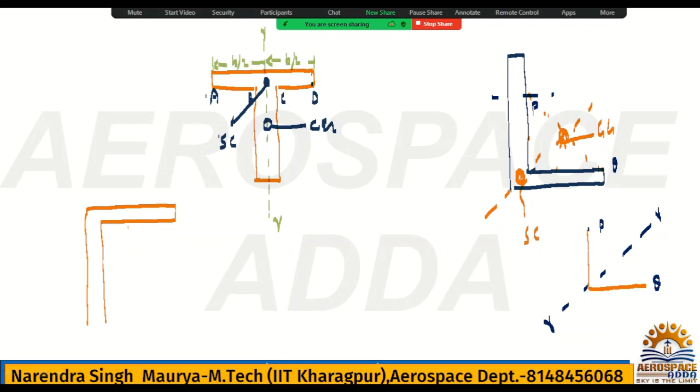Because see, very simple. This portion is what? Mass distribution here and mass distribution here. It is not symmetric. Yes or no? So it is sure the CG will not lie on this below section. In fact, CG will not lie over this upper section. In between somewhere CG will be lying. It is not necessary that CG will always lie inside the structural member. CG can lie out of the structural member also. In fact, shear center also is not necessary to lie inside the structural member. It can lie outside also.